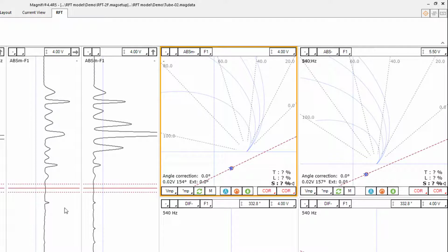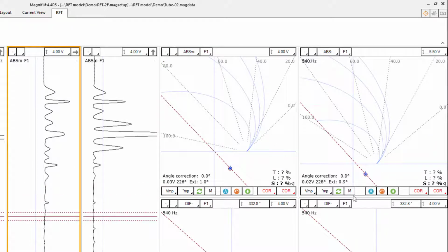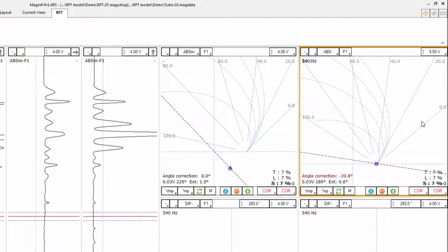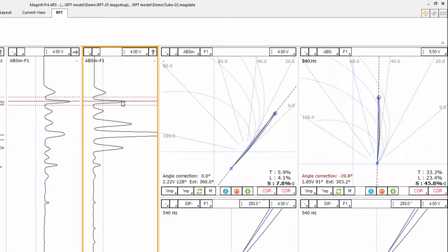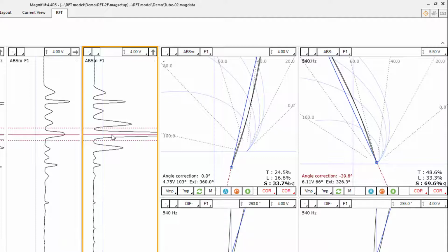Again, I can just set my cursor in a sound area and normalize on the old voltage plane model. The sizing curve remains static, but now because the material is more attenuating, when I select the 40%, I oversize the defect because I have more phase shift than the original calibration. So instead of 40, now I'm overestimating this at about 46%, and my 60 is at 69%.